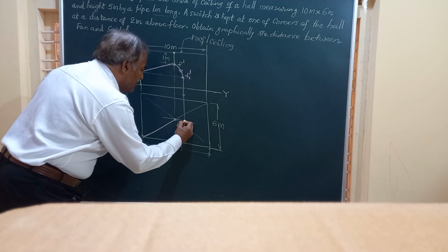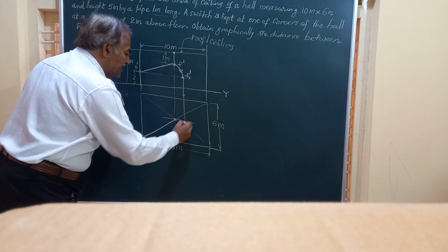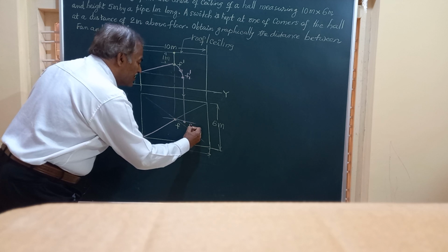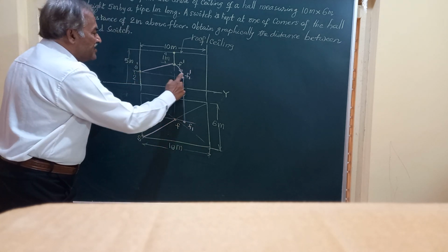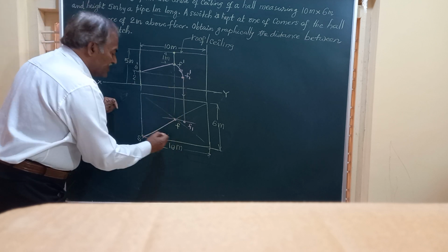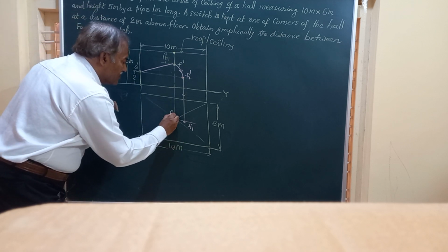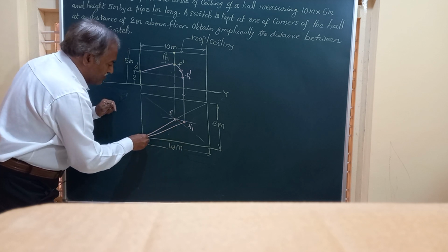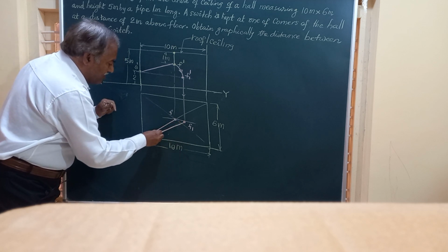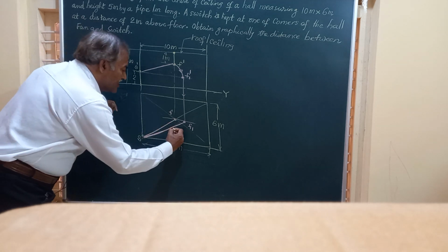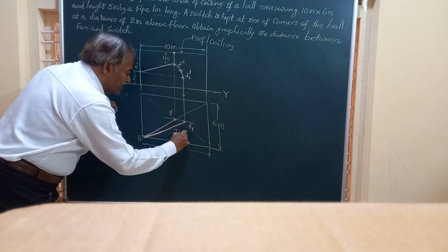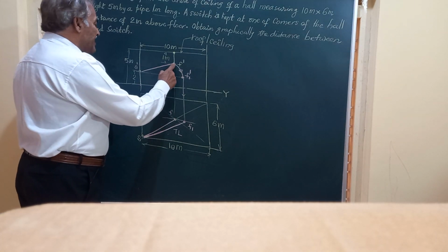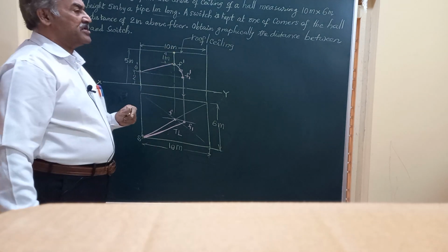The point where those two meet will give you F1. Friends, the front view is parallel to HP, so the corresponding top view gives the true length. If you join S to F1, this will give you the true length of the line, or the distance between the fan and the switch when measured graphically.